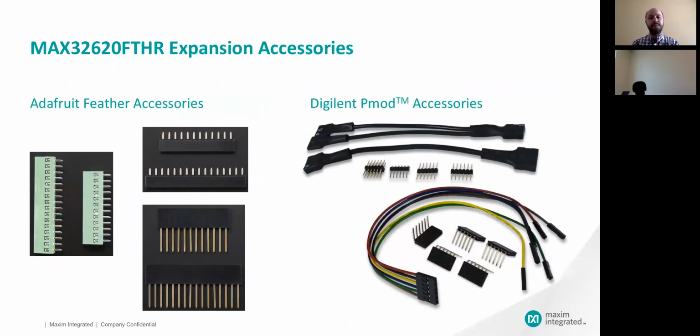And again, because we're using standards, in addition to connectors, there's a variety of accessories you can get. One of the reasons we don't include the feather headers is because you may want to install a different header. You may just want a straight pin header for going into a breadboard, or you may want stacking headers or low profile. And Adafruit even has screw terminals that you can solder directly into those. It ends up being a lot easier to solder in a new connector than it is to remove one we soldered in for you. So we just choose to leave those empty and let you install whatever you want there.